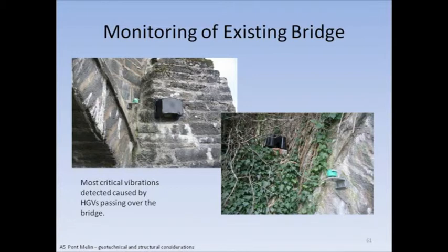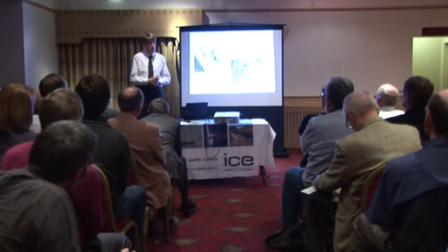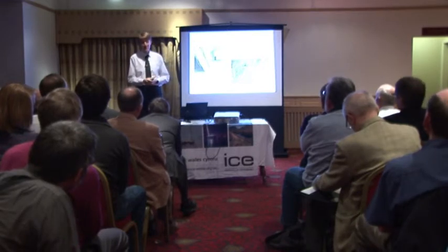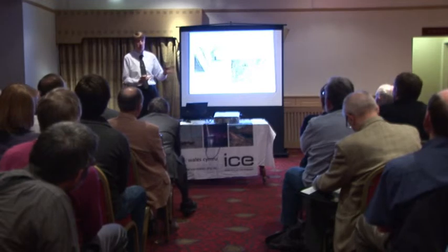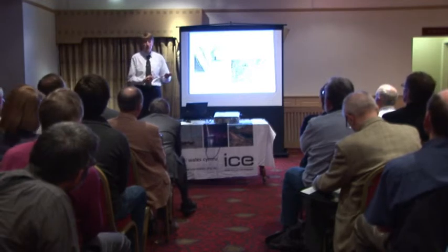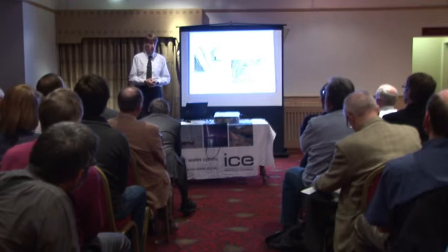And during the piling operation, which was the main concern for it, they didn't reach or go near those values that were picked up on the bridge, which actually seemed to occur with the passing of HGVs, and probably due to the slight hump in the bridge and possible lift off of an axle of an HGV going over the bridge.